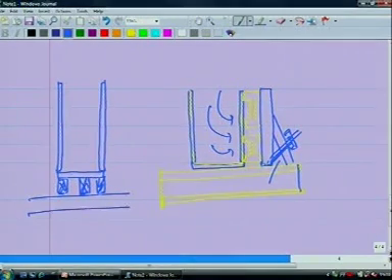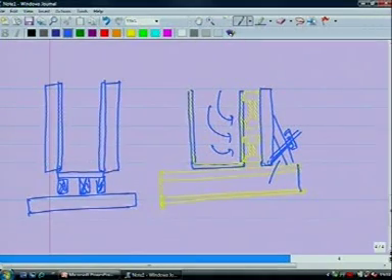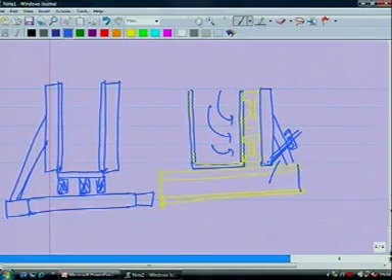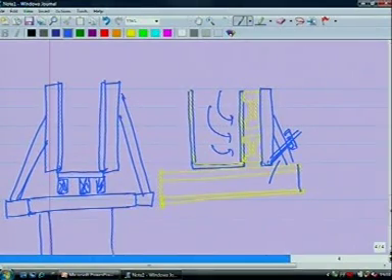Then you have another layer of timber here, and this is the beam sides made of timber, and then you can support it here, something like this, with the timber itself, and then you have two layers of maybe props. So do you understand this?